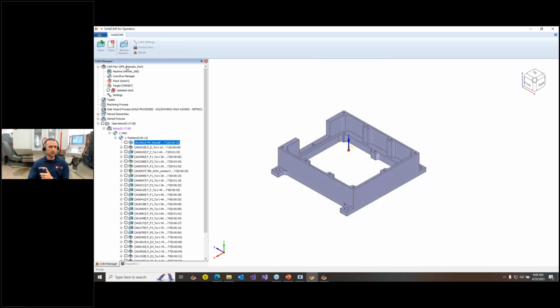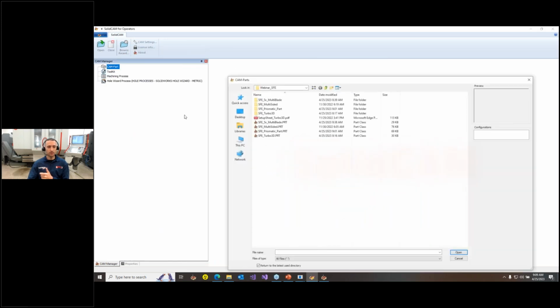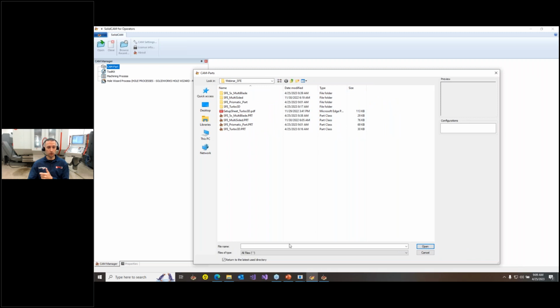Maybe I kind of blew past it, but you are opening up SolidCAM part files. So you're opening up either PRTs, PRZs, or internal CAM. Interesting note: internal CAM parts are accessible. The only problem with that is you need to have SolidWorks installed on the computer, because reading in and out of SolidWorks files requires SolidWorks. So that is a limitation.